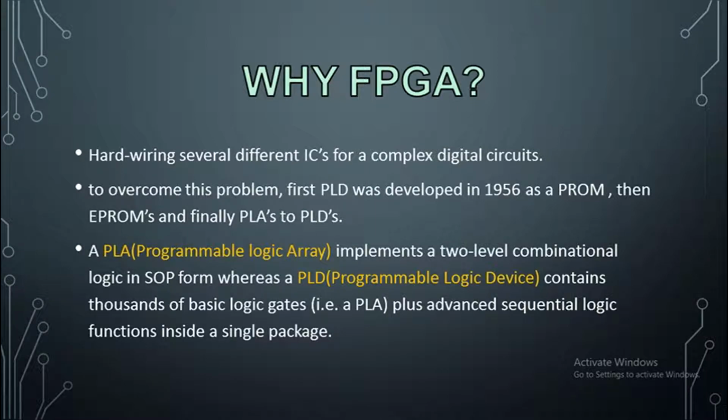To overcome this problem, the first PLD was developed in 1956 as a PROM. Then came EPROMs and finally PLAs to PLDs. So what is a PLA? A PLA, a programmable logic array, implements a 2-level combinational logic circuit in SOP form, where SOP stands for sum of products, whereas a PLD, a programmable logic device, contains thousands of basic logic gates plus advanced sequential logic functions inside a single package.